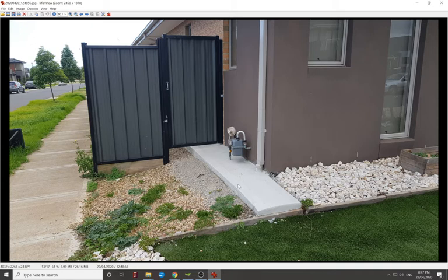And there's definitely no doubt you can't have the land graded towards the house and water pulling up against the house. But actually having a slab around the house, what I've read is that it's supposed to be 1 metre wide and 50 mil fall, 1 in 50, which is quite a steep fall too. 50 mil over 1 metre is quite an aggressive fall away from the house.